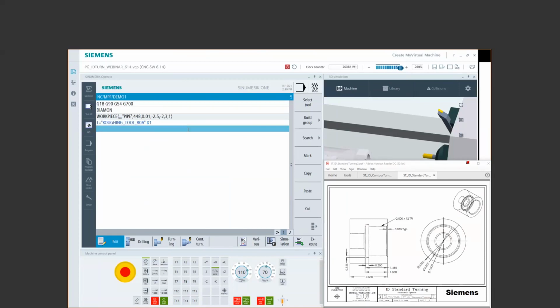But traditionally, if I have a turret or a tool post, no M6, the T call by itself is going to be enough. I don't do prefetching in this scenario, right? So with that case, then I'm good. If I do another T call, it's going to spin the turret to that new location.